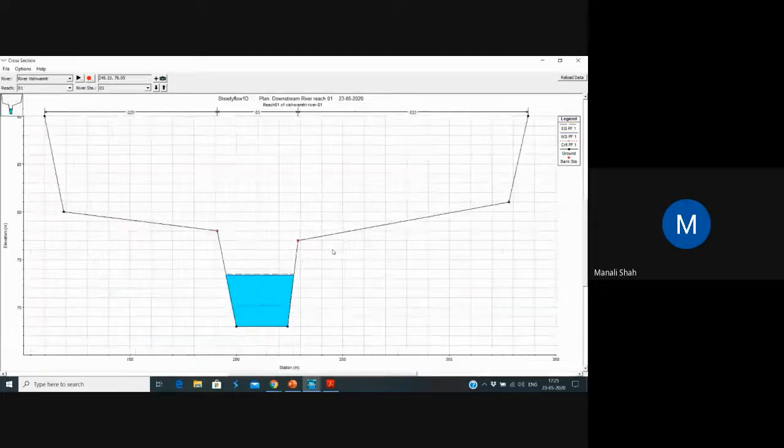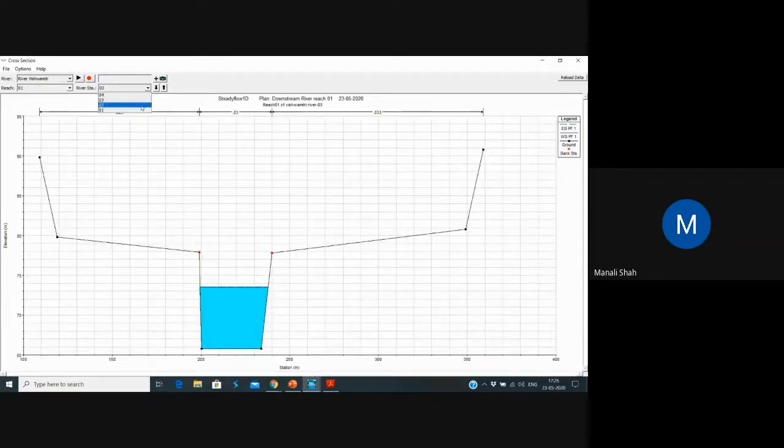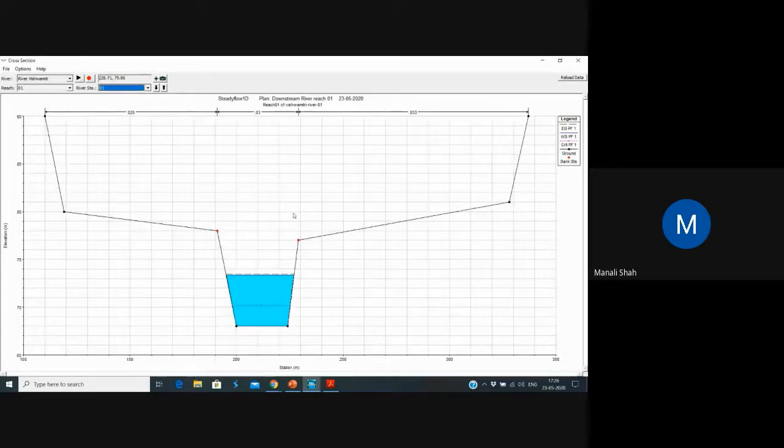So the elevation is 73.48 and the ground point is 227.05. But here you can see that in every cross section, the water is inside the cross section only, right? It is not lying over this. If the level of water is above this ground point, suppose it is lying up to this level, then you need to calculate the elevation of this point, and when you subtract these 2 points, this much amount of wall you need to construct. Are you getting what I'm trying to say?